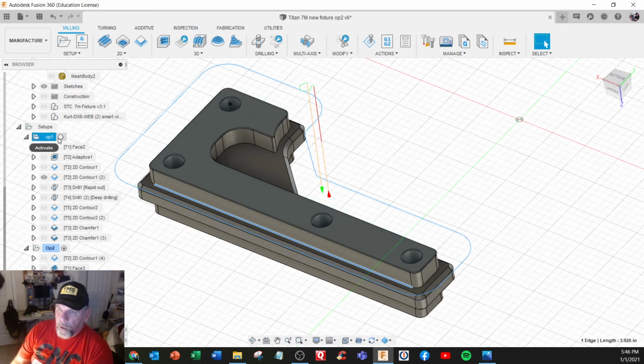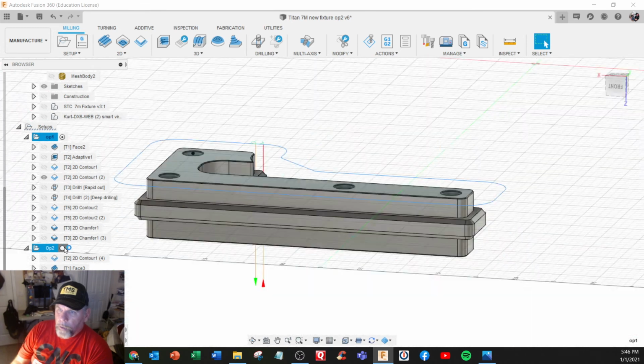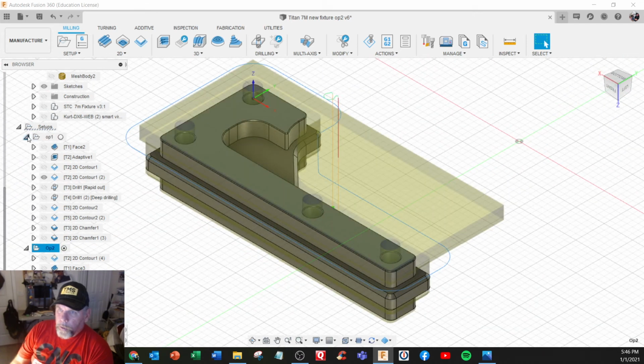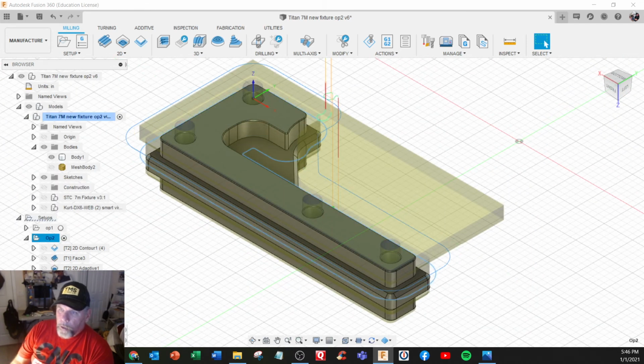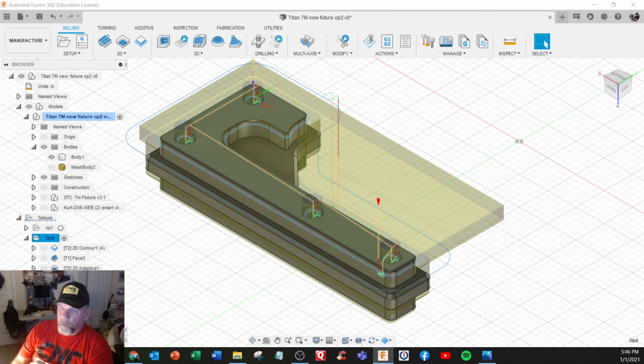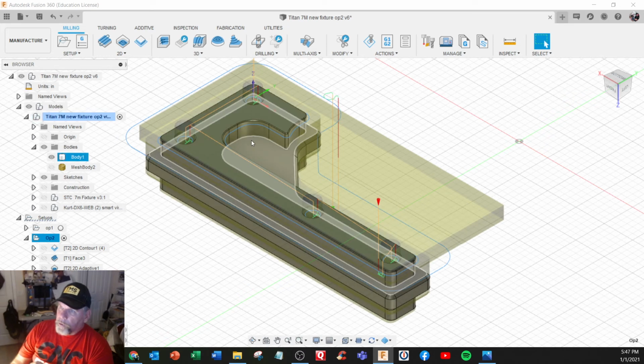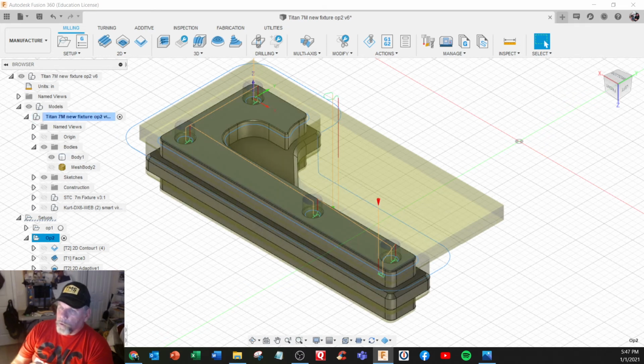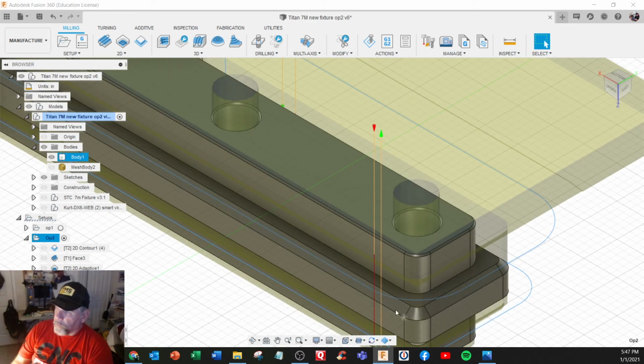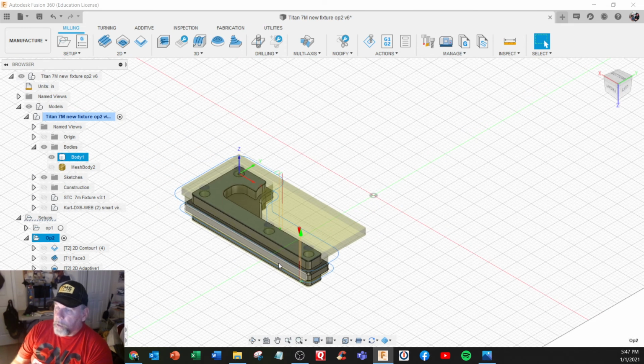So I'm going to turn on operation 2 again. Shrink this up. We got contour, and then we just do the 2 chamfering operations from the first side, which would be chamfer up the top of this and chamfer these small holes. And then we'll do the heavy chamfer on this surface here. And that'll be the end. So you just need to copy these 2 operations.